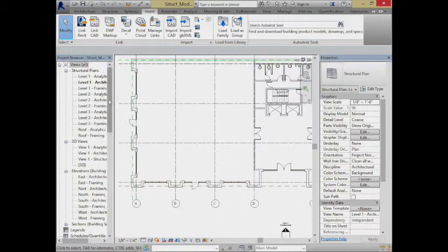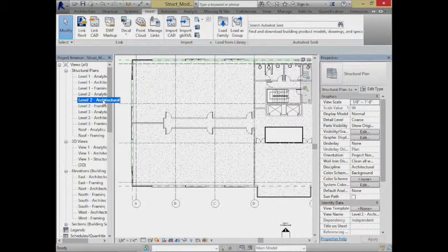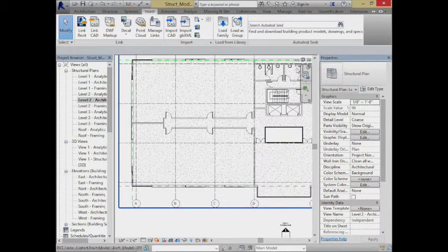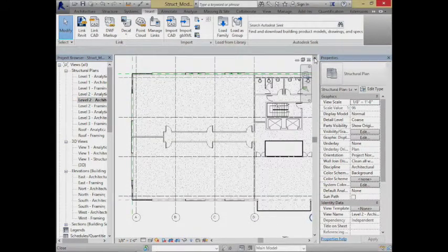Then go up to the second floor. Hopefully these are relatively good locations. After a while, you start thinking about just the best way to put the grids. Often grids aren't right at the outside line. Often the structure is just a little bit inside from the outer skin of the building. And that's the idea here. We're going to hold everything back just a little bit. We're going to have some columns at different locations that are a little bit less impactful, and put some of these common walls in here.